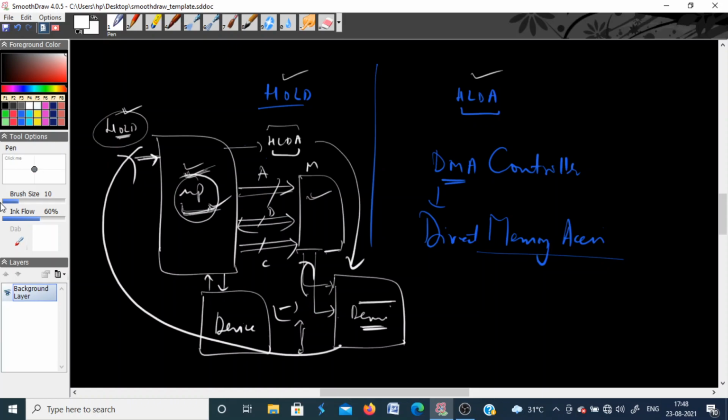There is one more pin which I think I have not discussed, called the ready pin. This ready pin is basically used to delay the processor if there are some slow peripheral devices connected to it. The processor goes into a wait state for some clock periods. So this is what the internal architecture is about.